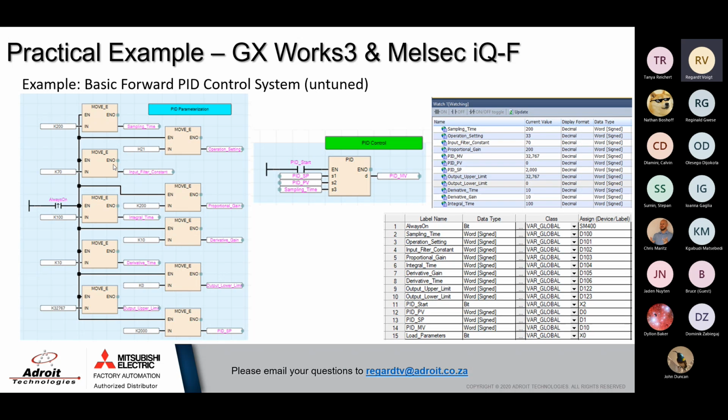If you have a question, what's the importance of understanding what TI means, or what KP means, or why do you need gains, it will be answered by this section here. These are the parameters that you'll put into the PID to tell the PID how to react to certain errors in the plant.